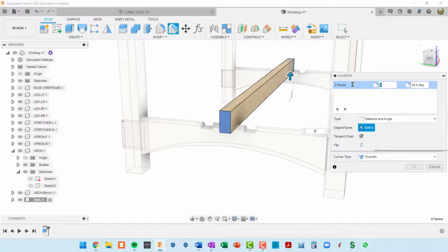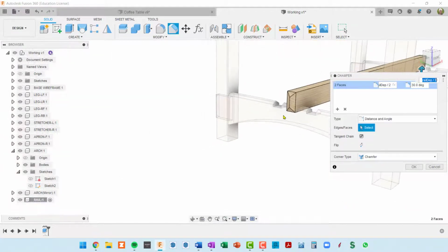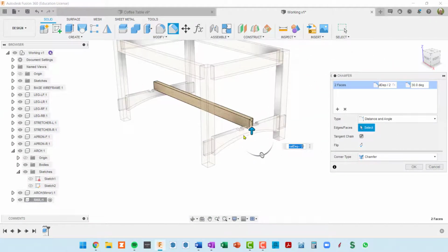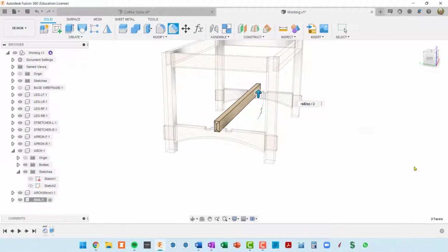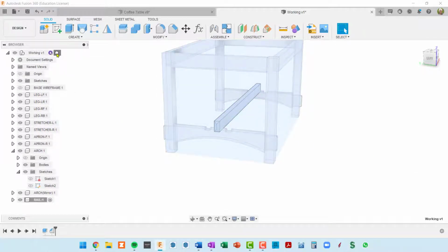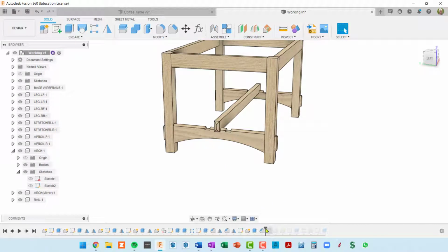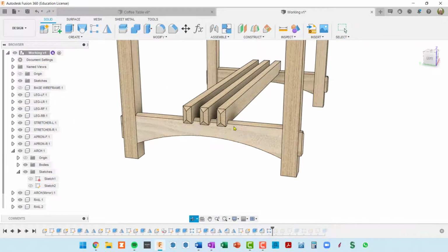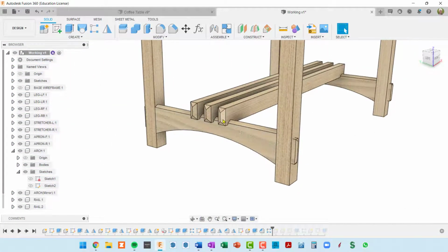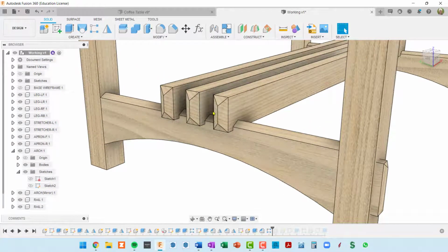And then we want half of our rail thickness. So I'm just going to type in rail, pick depth, divide it by 2, and our preview is showing us what we want on this end and showing us what we want on this end. So one chamfer command, we did both ends. So I'll click OK. And now we can go back to our top level timeline. And let's just move out one piece at a time. There we've reproduced our 3 rails with a rectangular pattern. And since we got our chamfer in before the other 2 rails were created, we get that for free.